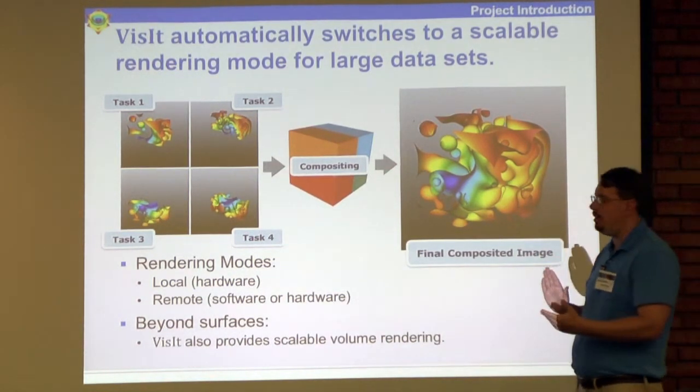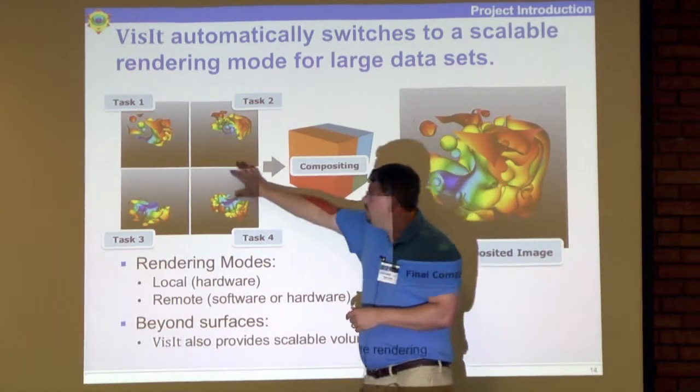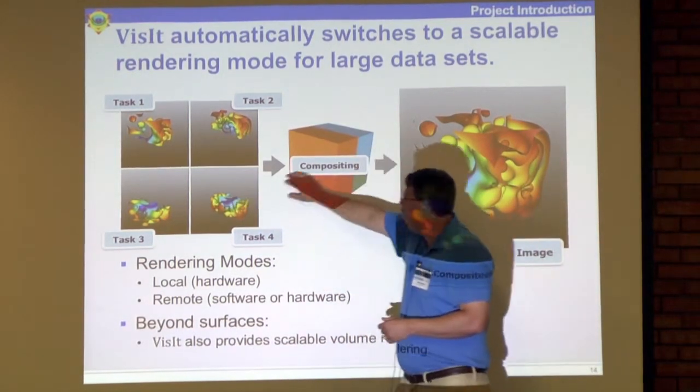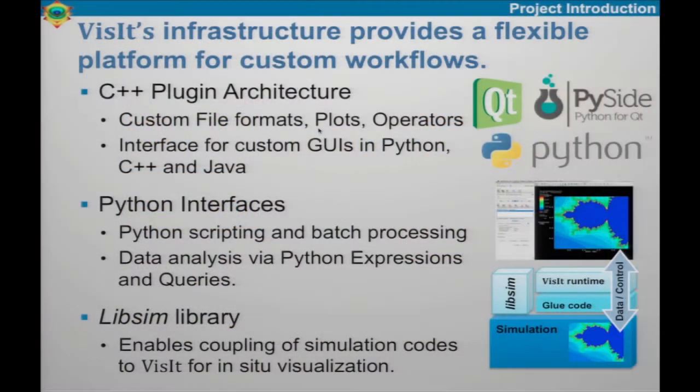You can use that depth information to take these sub-images and, the phrase they use here is, composite them together into a single image as if they'd all been rendered on a single machine, on a single MPI task. So the idea, going back a slide, is that it does this parallel rendering, and then sends an image over the network. As the camera changes, it sends a new view frustum over to this parallel server, it generates a new image, and then sends the next image back.